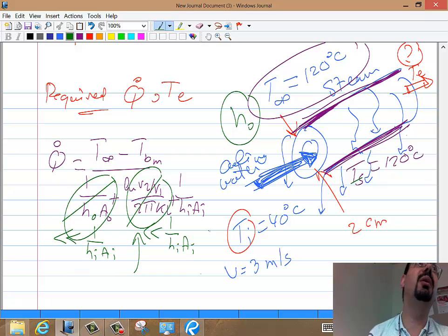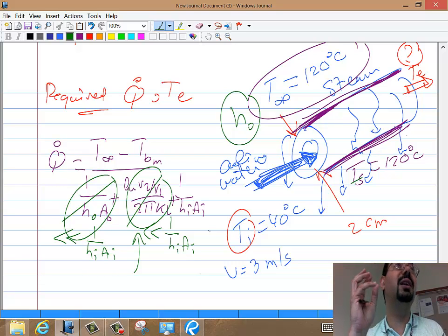You just have to look at the number and maybe make a visual inspection to say, is it worth it? Do I have the time in the exam to calculate this or not? And in real life, by practice, you would know that you would do this calculation many times, and this pipe wouldn't matter. Let me just go for the, where is the beef? And the beef would be the convection. You don't want to add the 0.001. So you will get that sense of which one is really the biggest resistance.